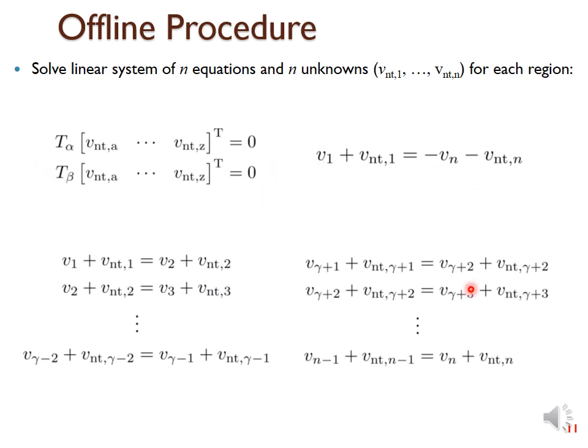All the other equations are obtained by solving the optimization problem that the DC link utilization should be maximum. This one means that the lowest and largest values at each instance should be equal to each other in absolute value. These expressions impose that the lower gamma minus 1 voltages are all equal to each other. These other equations impose that the other n minus gamma elements should also be equal to each other.